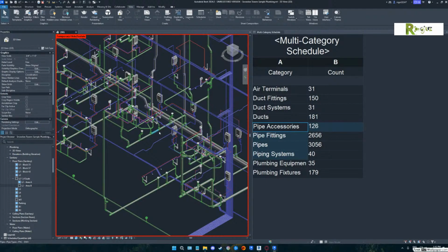Here's what I want you to think about. You don't have to do it for every pipe system in there. If you scroll down to where the pipe systems were, keep going, you're going to find there's a lot of them in there, because there has to be one of every type, even if you don't use it for vent, sanitary, hydronic supply, hydronic return, all the four fire protections, domestic cold and domestic hot, even if they're not being used. But see, remember, I told you, this is what I do when I get a file from someone to find out about the file.